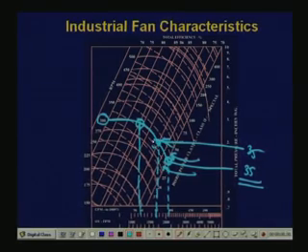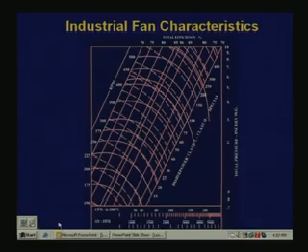You see, this is the 30 curve, this is the 40 curve. It is actually a nonlinear variation, because from 50 to 60, 60 to 70 it is gradually getting closer. So, this is something like 31, 32, slightly reduced actually. So, this is how you get those figures from an actual pump characteristics.